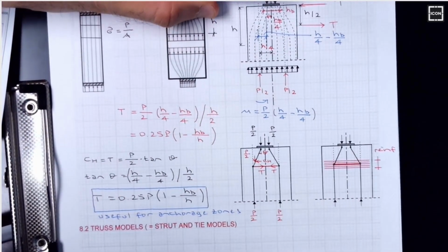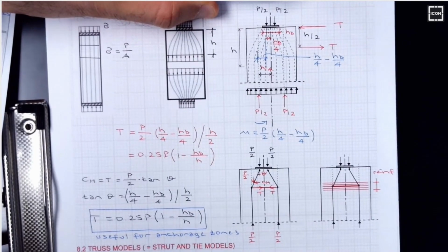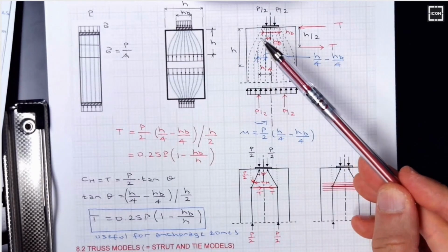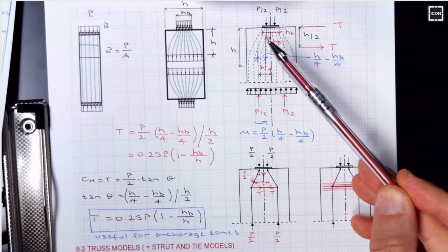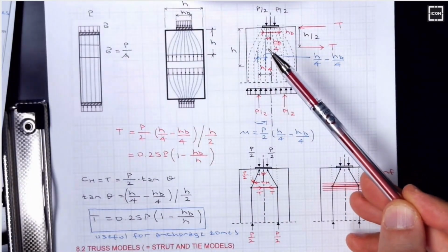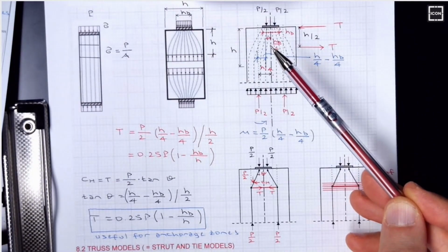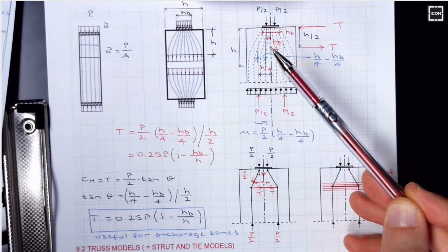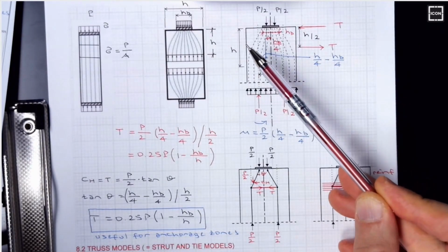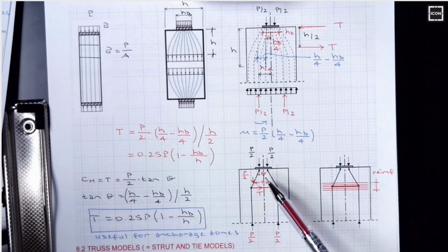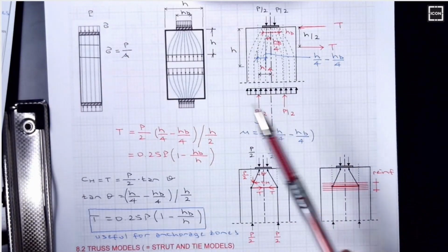So these are just some light introduction of what this idealization is. It's nothing but idealization of the stress flow. So stress flows, and you have to see that this is what is required. In the old days, design used to be done sometimes by architects, sometimes by experienced people with the capability to see stress flow. So this is all based on visualizing stress flow, knowing H would be the disturbed region, and creating a logical truss model within that region.